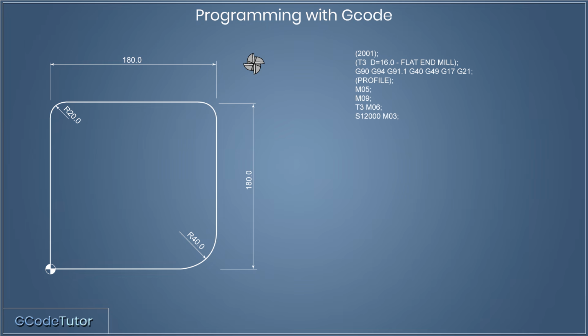With G-code, an S value normally refers to the spindle speed or the rotation of the spindle per minute. Now routers tend to run quite fast spindle speeds since we're cutting wood. So I've selected a spindle speed of 12,000 RPM, and the M code M03 tells the machine to turn the spindle on in a clockwise direction. If we were to go anti-clockwise, we would use M04.